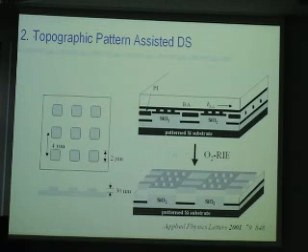So as I explained before, in this matrix region we can create the in-plane cylinder. But under this mountain region, we can control the orientation, which is a standing up cylinder, which is more useful for real applications. So for that, after we fabricate this film structure, we did oxygen plasma reactive ion etching to selectively remove one domain to fabricate the nanoscale membranes. That's what we did.